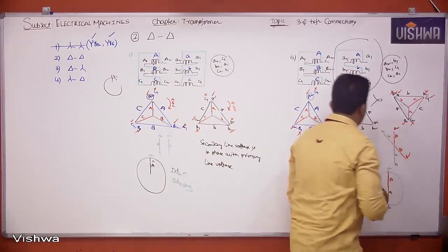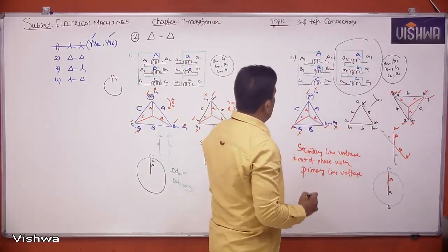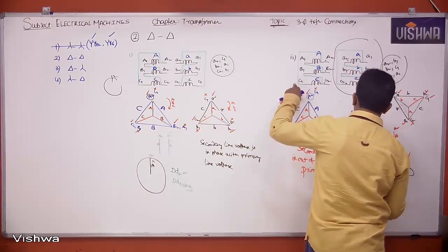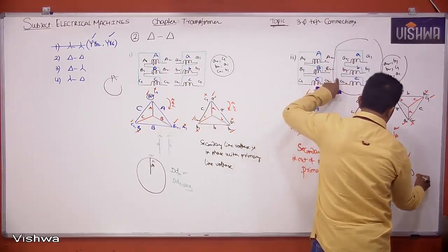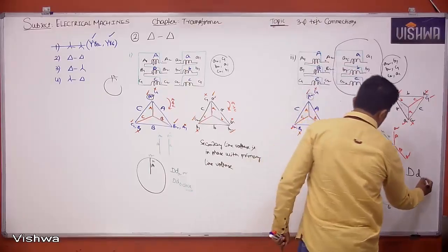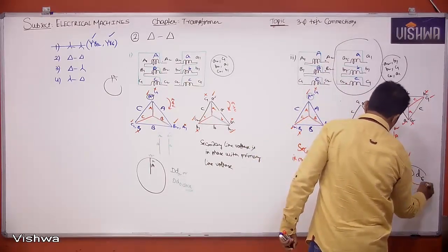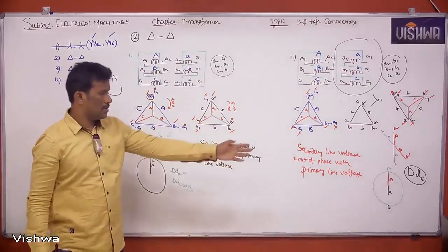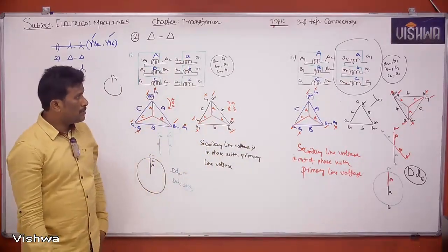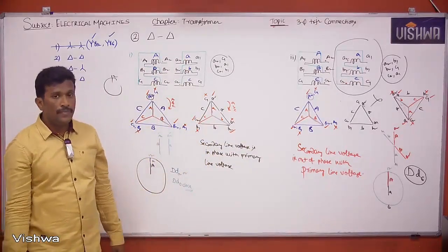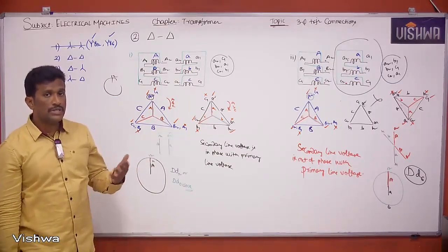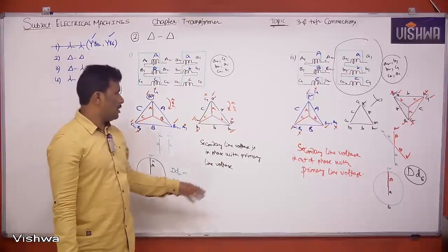6. Okay. Now what is the connection name? It's nothing but primary delta capital D, secondary delta small d, DD 6 o'clock. This is DD 12 o'clock, DD 6 o'clock. Okay. If you observe clearly, previously also in star we got YY 12, YY 6 o'clock. YY 6 we got. Here DD 12 I got, DD 6 we got.